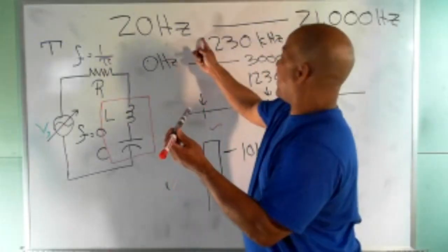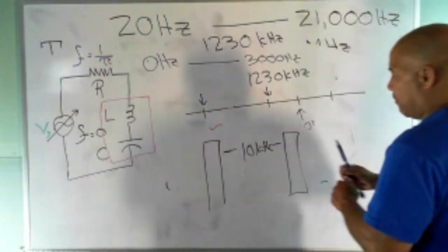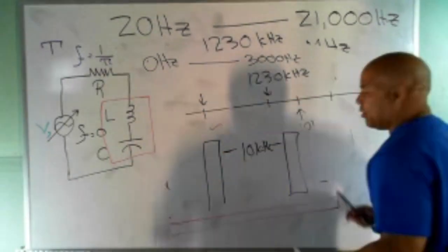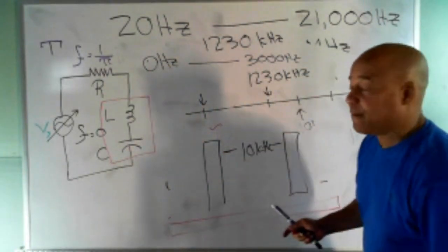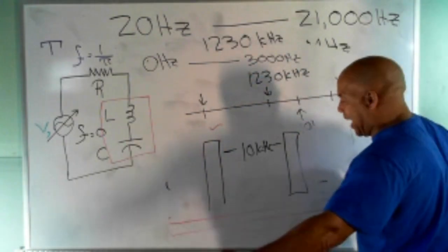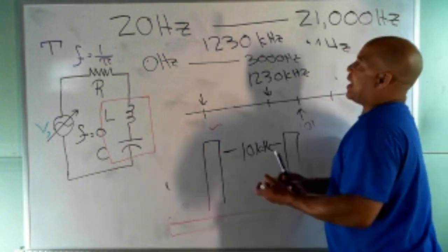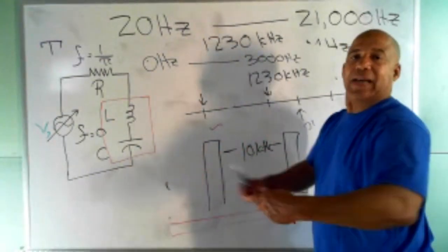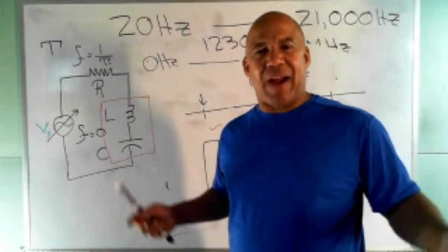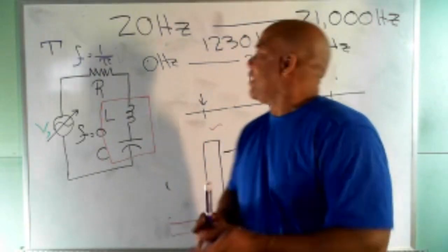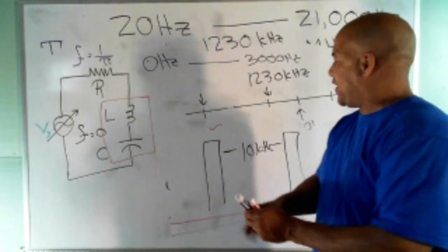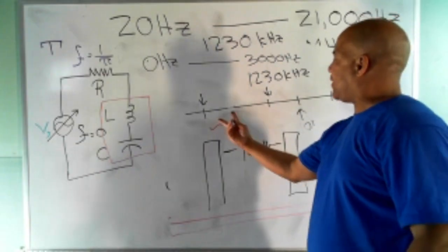That represents this. I'm trying to get something that's 21,000. I'm using kilohertz like they were feet. I'm trying to get something that's 21,000 feet or kilohertz wide through a space that's 10. I'm going to cut half this off. You're throwing half your information away. That's the reason why when you listen to AM, it sounds so crappy. Because they actually have to cut part of the signal out in order to get the information in that amount of bandwidth. I only have 10 kilohertz of bandwidth.